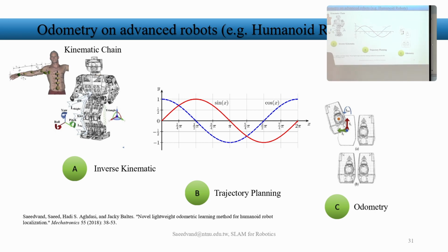So now we extend this knowledge to the humanoid robot. We have the same scenario on the leg. For example, I want the robot to bring its foot, the end effector, end point of the feet, forward, like the right foot forward, without z. So you can increase the x, and the robot should be able to achieve this x. You increase the y, for example, you increase the z, then you can achieve any 3D coordinate with the robot leg that is achievable for the kinematic chain that you have.